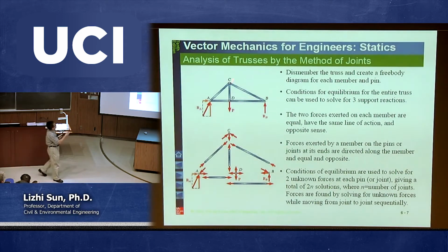And that is something like this, right? So we have the rigid body here, and there's an applied force acting on point D. At point B is a rocker, that's why we give a reaction called RB, which is unknown. And then at point A is a pin support, that's why we have the reactions RAX and RAY. So for this free body diagram, there are 3 unknowns, RAX, RAY, and RB. This is a typical 2-dimensional rigid body problem.